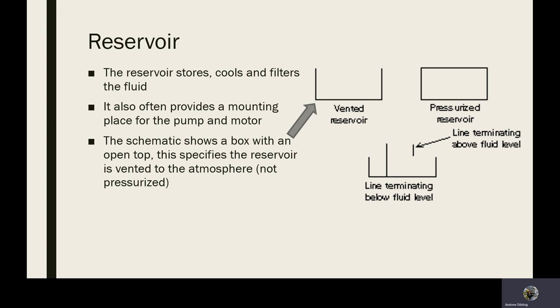I know that the sealed systems that are inside the pitch rams of 3 megawatt wind turbine generators carry 300 bar, 300 atmospheres worth of pressurized fluid. Now, it's a closed loop system, so there's only 30 liters in that system when it's shut off and in place, but that system is enough that if the power is lost, it can revert to its park position on the rotor, which is to snap them 90 degrees out of the wind.